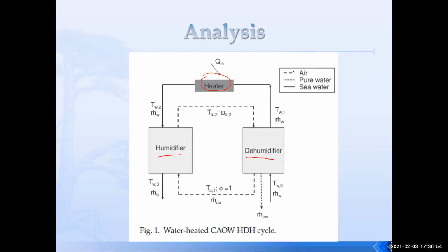So we do a couple of things: cooling, in addition to taking the energy rejected by the compressor or the condenser of a vapor compression cycle as the source of heat to run a water desalination system, so that we protected the environment from having high energy dumped to the surroundings in the form of heat. And we have made use of that heat to run a water desalination unit.